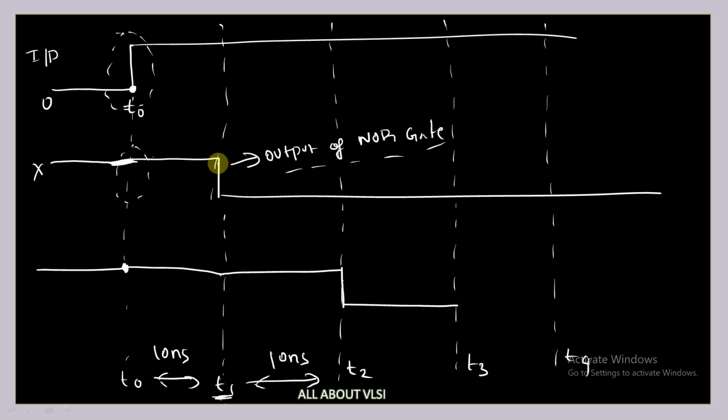Now what is 0 XOR 1? It is 1. So this change is happening. This is 10 nanoseconds now. That's why 0 XOR 1 is 1, and this is also happening after 10 nanoseconds only. So the output is 0 for only 10 nanoseconds.